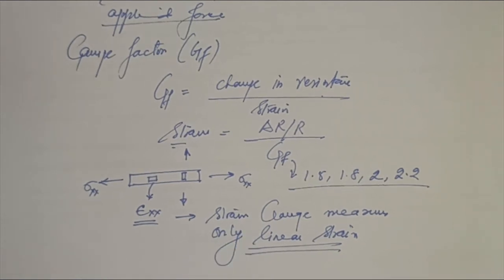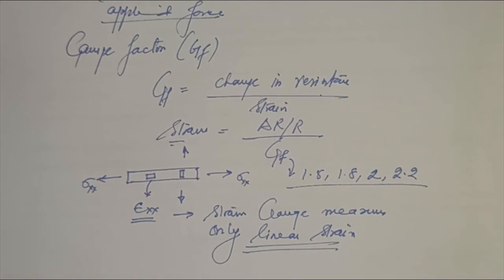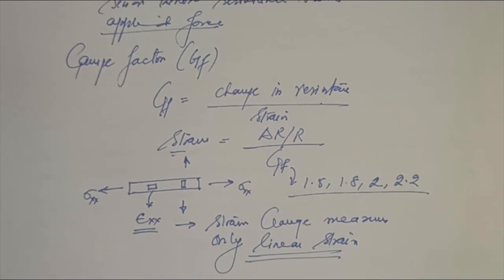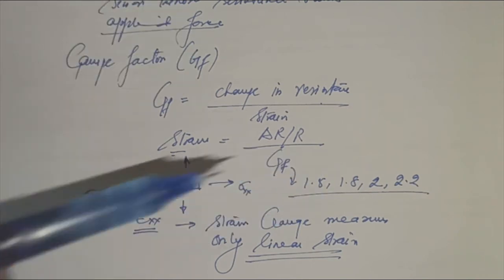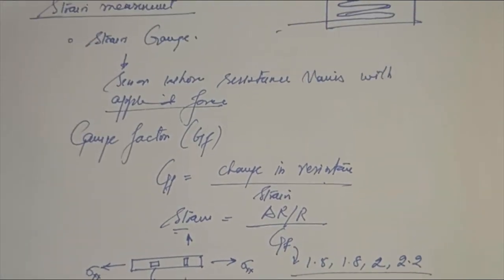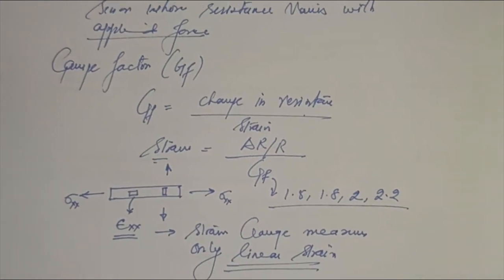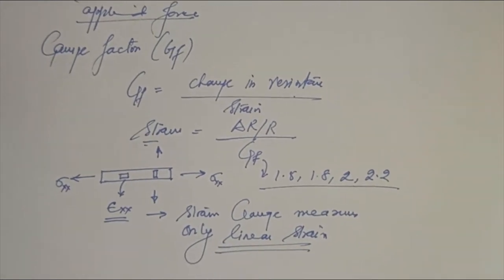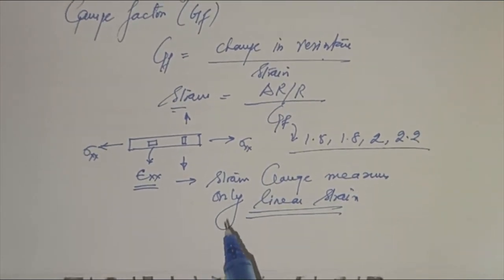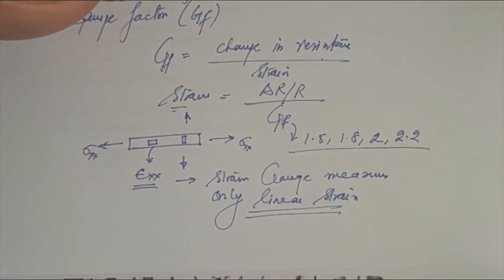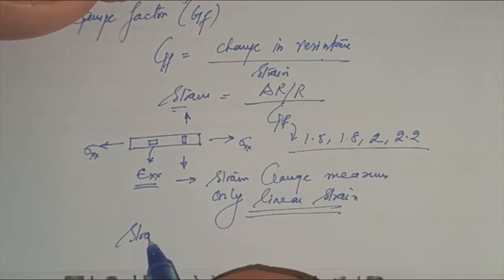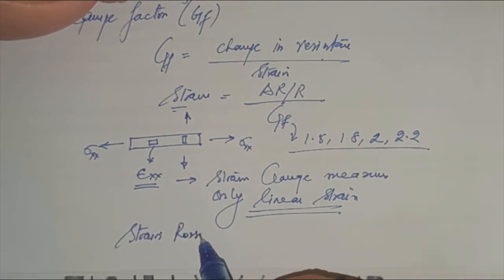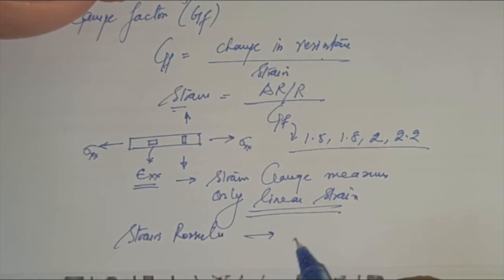So if it is like that, then how will we be obtaining the shear strains? Shear strains are the effect of two surfaces rubbing together. So as an effect of strain, a whole of the body moves. So how will you obtain the shear strain? There is a technique people used to use by which they obtained shear strains, and shear strains are obtained by strain rosettes. So strain rosettes will give you shear strain.